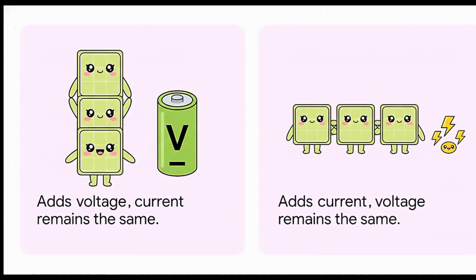And here's a fun fact. Because every inverter has strict limits on the power it can safely handle, we have to wire these panels up like a giant logic puzzle. Sometimes we wire them in series, daisy-chaining them to boost the overall voltage. Other times we wire them in parallel, which keeps the voltage flat but boosts the current. Usually, a big rooftop setup uses a very careful mix of both, so we don't accidentally fry the whole system.